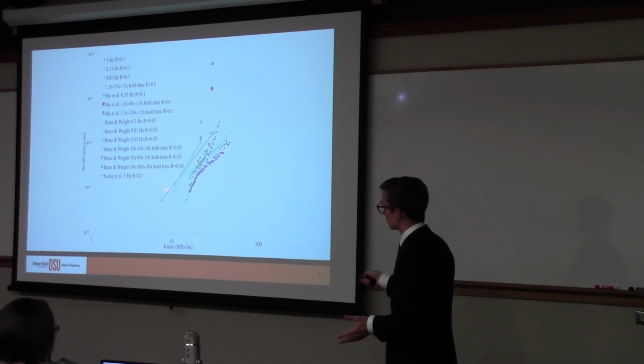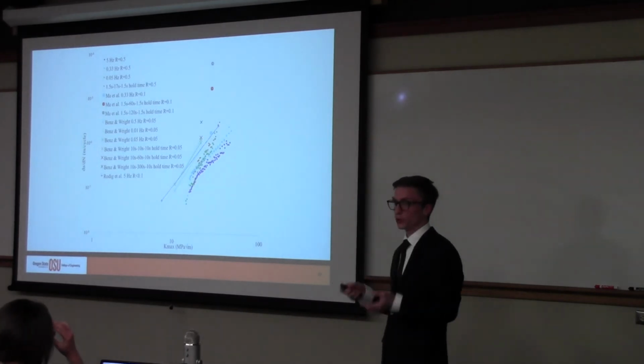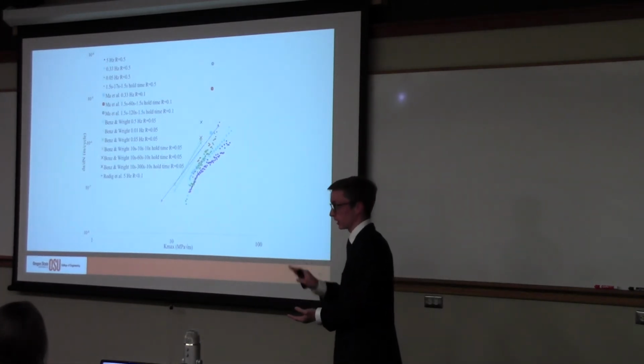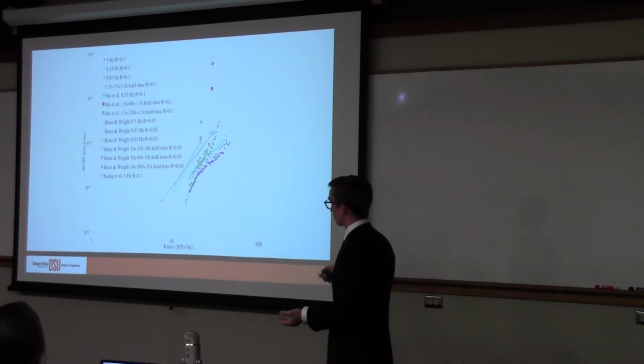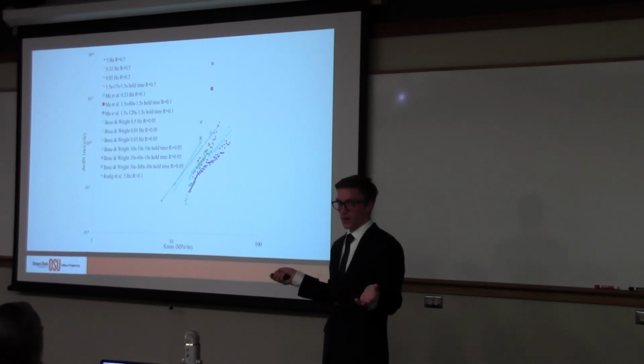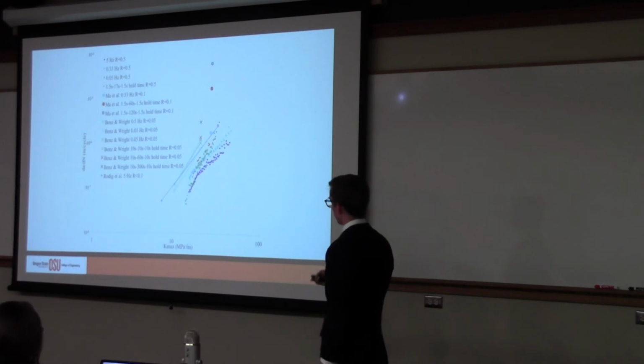to use these power laws that come out of this data to understand how fast the crack is going to grow per cycle, per day, per week, as we're increasing the power production. We can start to get estimates, and as long as we keep it below this threshold for time dependence, we're going to get the right mechanism that's going to allow the IHX to last for a long time.